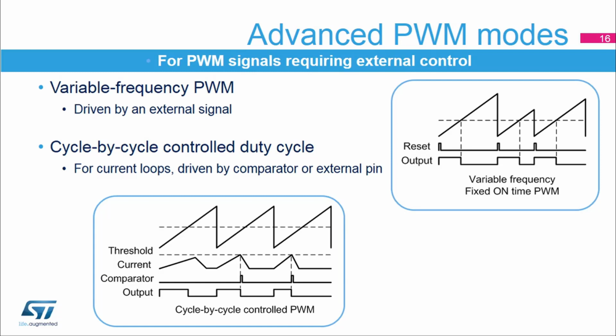The timer provides control for the on or off time using the compare register, while the auto reload register guarantees that the PWM will not stop if the external reset is missing, thus providing a safe control in boundary conditions. This technique is used for a variety of purposes, such as transition mode PFC or power factor controller for mains-supplied applications and current-controlled digital LED lighting.